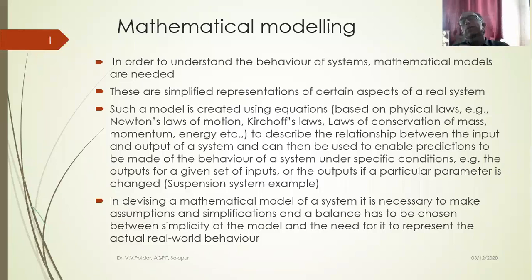So Newton's law of viscosity, I need to make use of. What is that Newton's law of viscosity then? Shear stress tau is equal to mu into dou u by dou y. If you remember, velocity gradient. So mu is the coefficient of dynamic viscosity into velocity gradient dv by dy or dou v by dou y, right? So what happens here when I'm moving the brush? What I'm experiencing is it becomes difficult for me to move the brush.